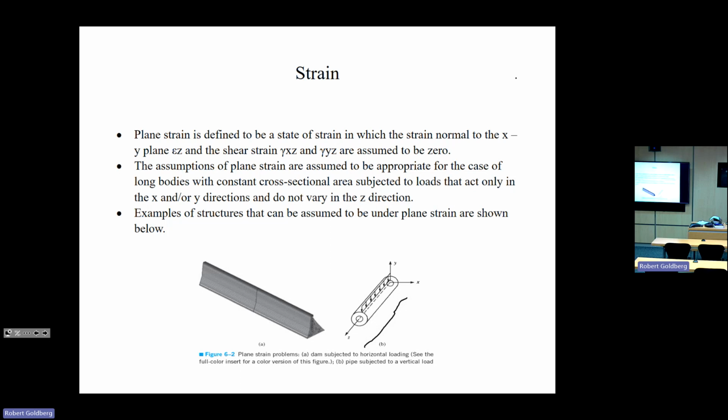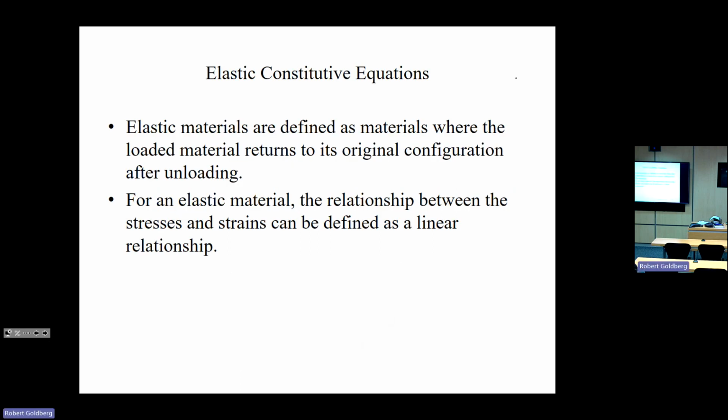So plane stress means that it's very thin. There's no stresses in the out of plane direction. Plane strain is for a very long structure, where there's no strain in the out of plane direction. So that's a whirlwind introduction to strain.